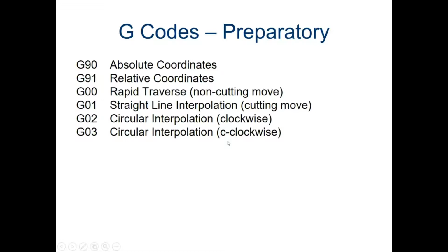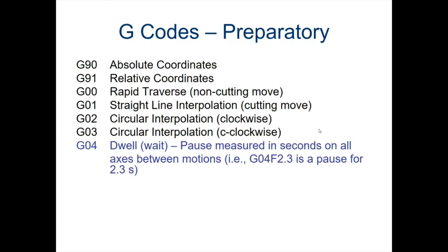And then G03 is counterclockwise, and that is also important as far as which way you want it to go, as to how it's going to cut. So you have to think through which way you are going to go, clockwise or counterclockwise. All right, so then there's some other codes we won't use very often, and I'll go ahead and click through.